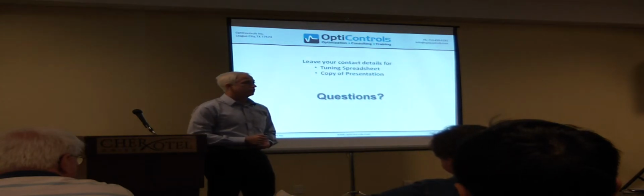Since you import and export data, obviously. Right. If that's a requirement to import export data, make sure your software can do that. If it's a requirement that you need this bell and whistle, you need to linearize pH loops, take a look for software that can do that. So yeah, I wouldn't recommend just one. I use Loop Optimizer and whatever else I need.